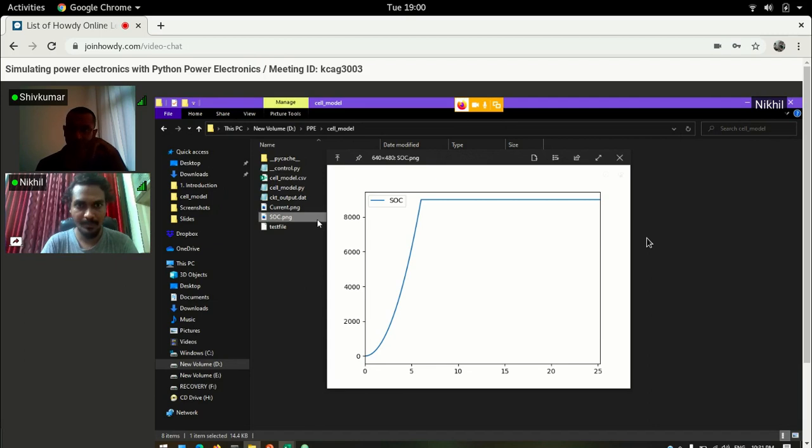Yeah, so that is what I wanted to say next. So you see what is happening here. The main thing here is the value of the capacitor you have chosen, which is 2.5. Now this 2.5 is ampere hour. That is not the same as farad. So you cannot choose the C value to be the same as the ampere hour. That value is going to be very different. And that is how you must map it so that this state of charge becomes maximum in 1 hour.